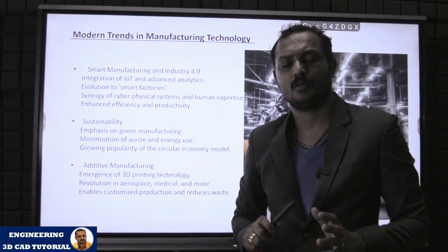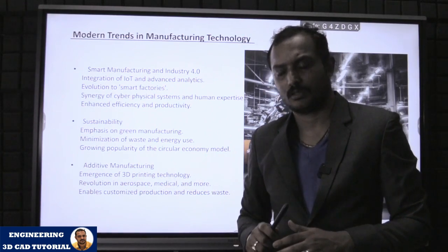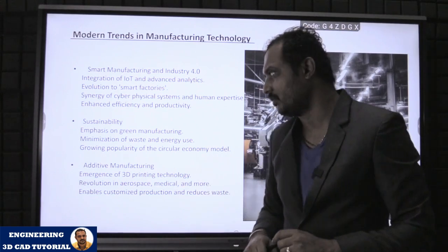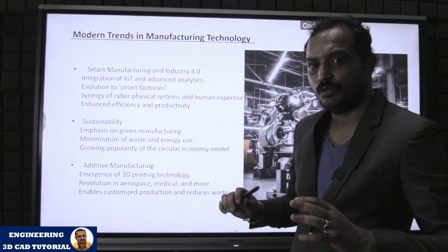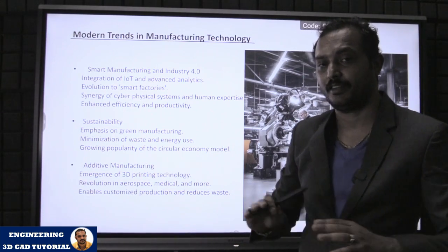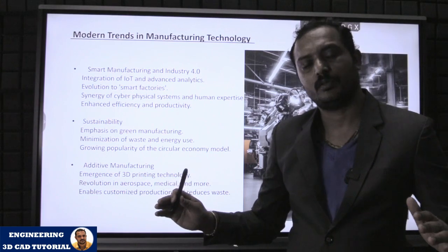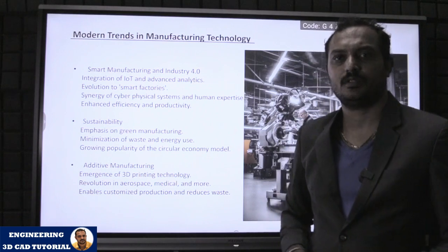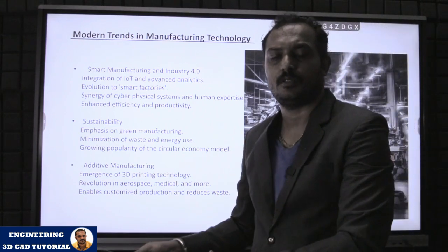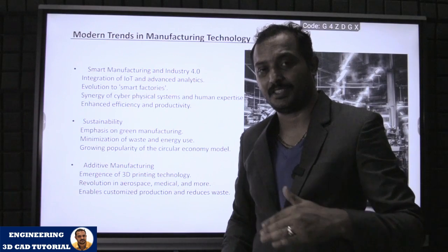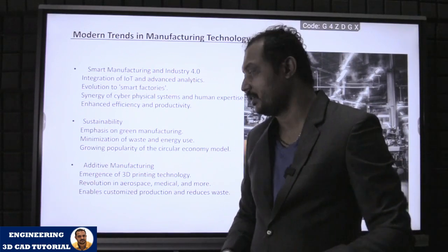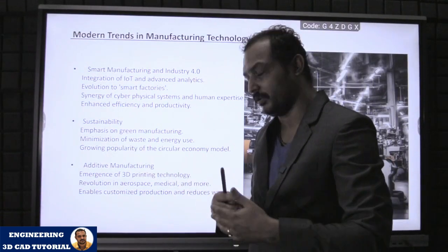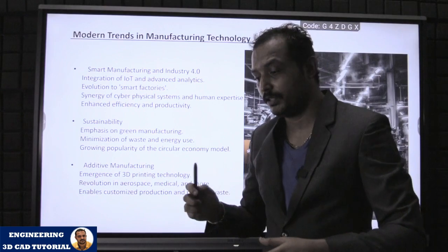Suppose you go to press tool, we are producing under certain utilization considerations. By using the utilization factor, the strip layout will be developed, so that we can consume the maximum. Suppose you bring 100 kilos of raw material, at least let us use up to 96% of the material to be transferred as a component instead of wasting it as scrap or left out material. So you utilize the maximum amount of material.